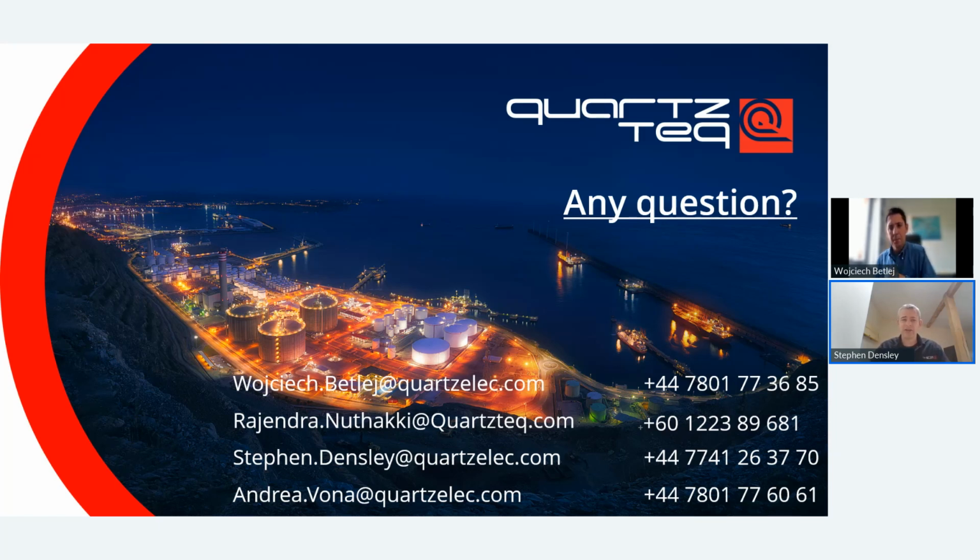I don't know if you can add to that, Wojciech. Yes, that's right. You can't really use PD to trip the unit as you would with a protection system installed, because it takes a while. You make that decision based on the data you measured when you have an online monitoring system installed. I'm not sure if that was the right answer, or did I answer it correctly?